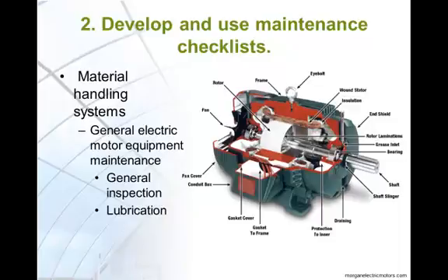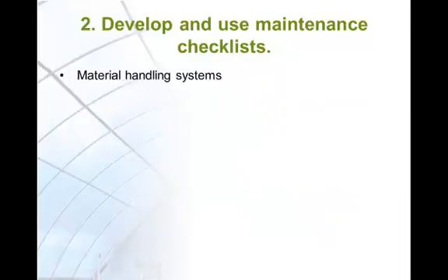Motors may or may not have grease fittings, and owner's manuals should direct you accordingly. Shielded bearings without grease fittings must be replaced at the end of the grease service life. Other motors may be oil lubricated, in which case the oil must be drained and replaced. More advanced maintenance requiring the disassembly and assembly of the motor may be required, such as drying the stator winding insulation. Consult your manual and seek qualified personnel. Each piece of equipment will have its own maintenance requirements depending on the device in question.